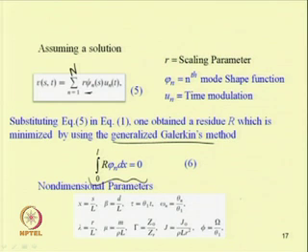Let us take these non-dimensional parameters: x equal to s by L, beta equal to d by L, which is the position parameter, and tau is the non-dimensional time, equal to theta 1 into t, where theta 1 is the fast mode frequency. Omega n, the non-dimensional natural frequency, is theta n by theta 1.